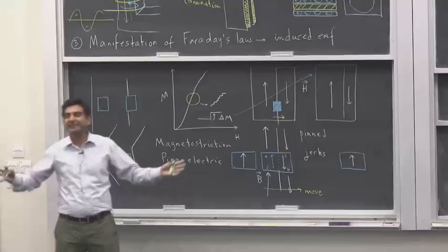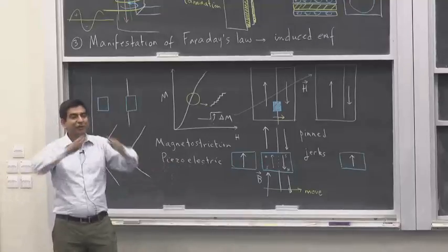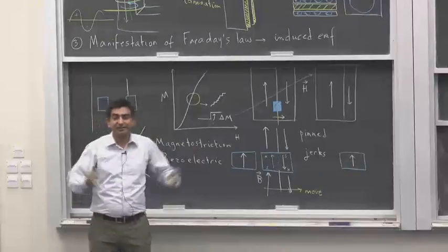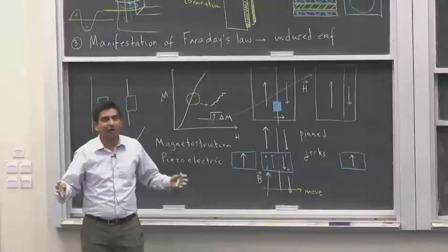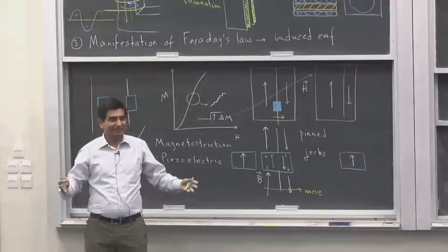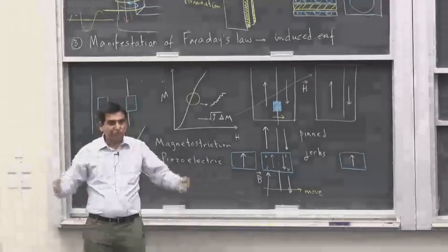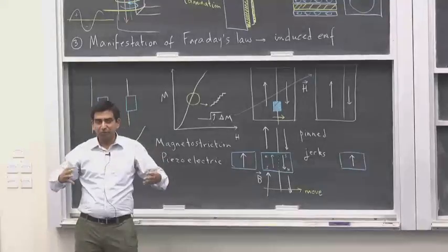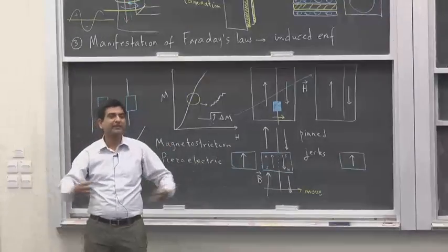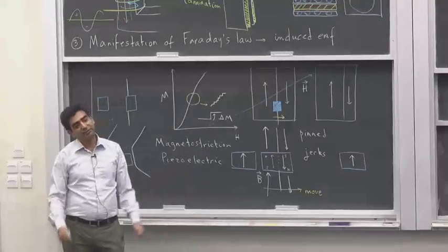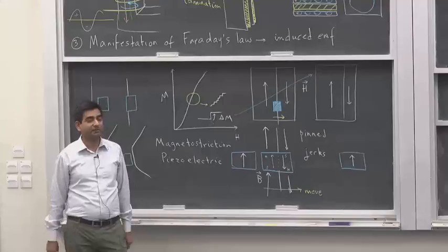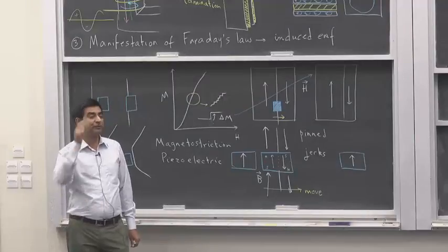And when it suddenly expands or contracts, there is oil that is circulating around the core of a transformer. It experiences a pressure. And when the entire big power transformer is breathing, because it's physically expanding or contracting, it will produce sound waves. It's going to affect the pressure of the air around it. That's going to produce a humming sound. That's why transformers are always noisy, especially the high power transformers, or especially the high frequency transformers.